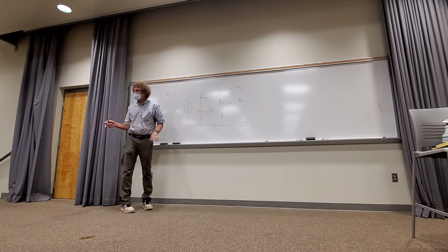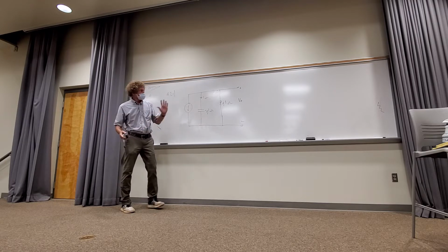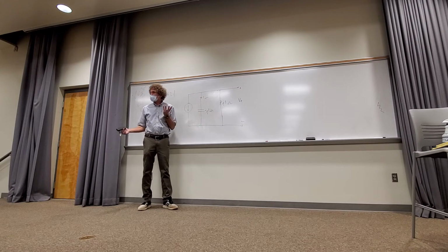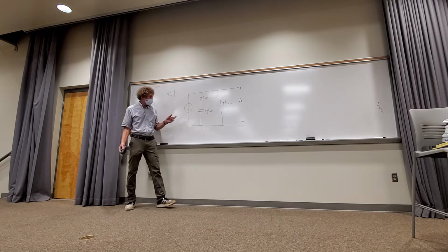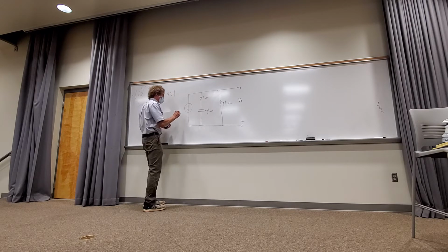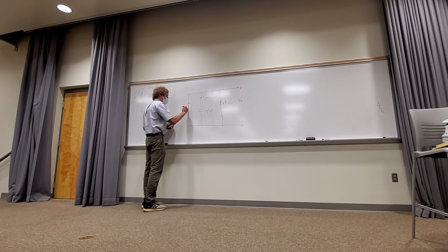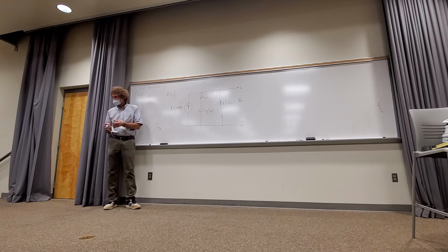All right, so here's what I'm going to do to make it easier on everybody. He asked, now, do you all agree we can find a parallel combination of those two? Right? And then you can multiply that by the current, which is 4. So I'm going to say this current going up is just minus 4 amps, just to make it a little easier, because you like current going up, right? So it's minus 4 amps going up.